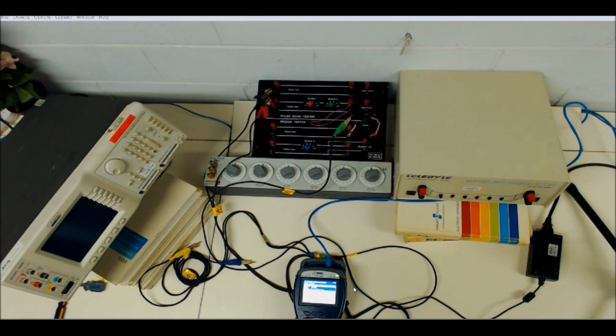So initially we have to run a resistive fault test. If we go into the default menu, we go to the display and select the resistance snapshot. As you can see, the tip to ring, the ring to ground and tip to ground are all earth. That means that they are all short circuited to earth. They are connected to earth. So we are experiencing a short circuit phenomenon in both legs, and that can be clearly shown by the value of the resistance in each of the elements.